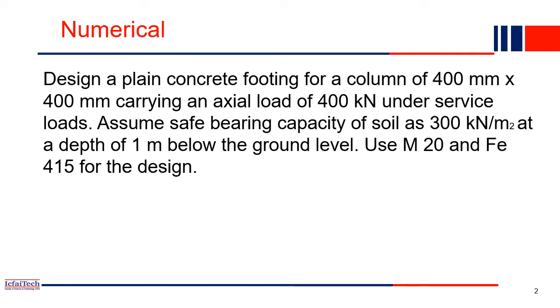So what is the question here? The question is: design a plain concrete footing. Every term in the numerical is very much important. Plain concrete footing means there won't be any longitudinal reinforcement. Although we have to provide nominal reinforcement, primarily the design should not be for the longitudinal reinforcement.